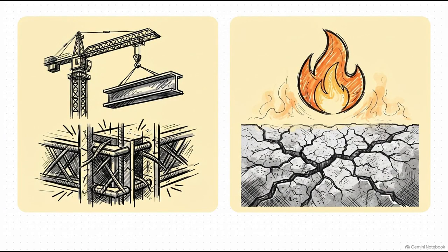Now, you might be wondering, why do we even care about that 0.012 diameter? Well, it's because these fibers do completely different jobs. Macrofibers, which are usually made of steel or a heavy synthetic, give you your structural post-cracking performance. Basically, after the cementitious matrix cracks, these fibers step up to continue transferring the load. That's why you'll constantly hear specs talking about residual strength, energy absorption, or toughness.